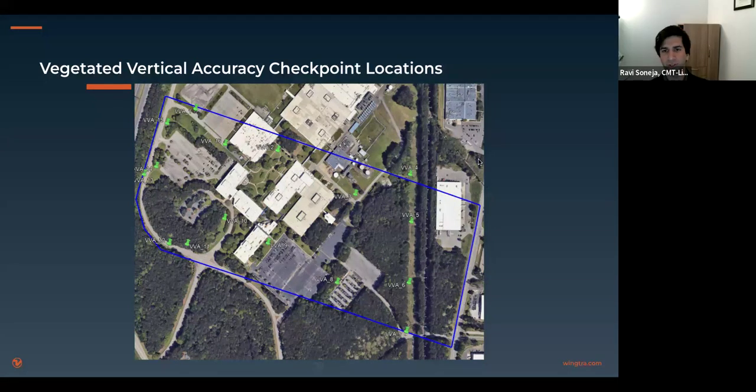That's a very good question. I think there's no one size fits all answer for a control network. It depends on the project, the size, the geometry, the terrain that you're dealing with. For something like this, generally we will target a nice uniform distribution and even spread throughout the AOI. For a corridor-based project,